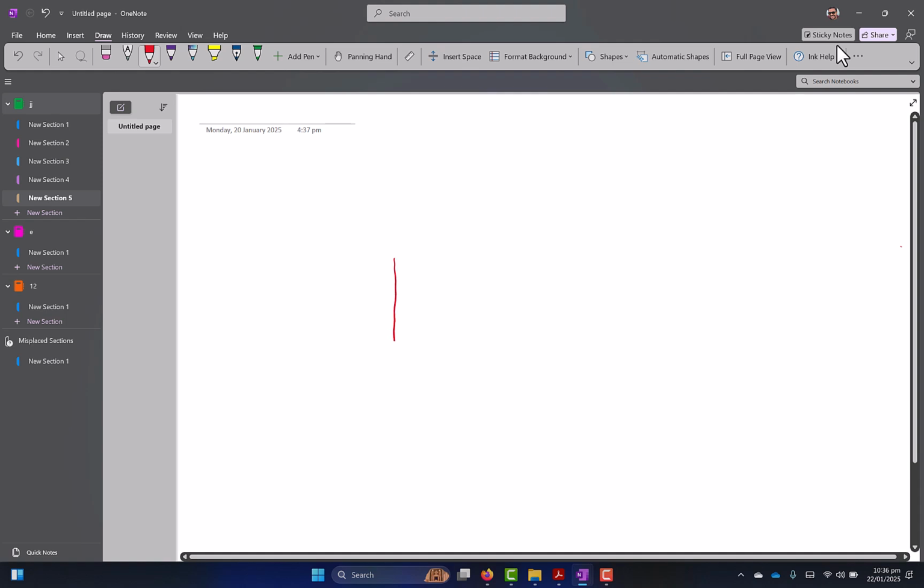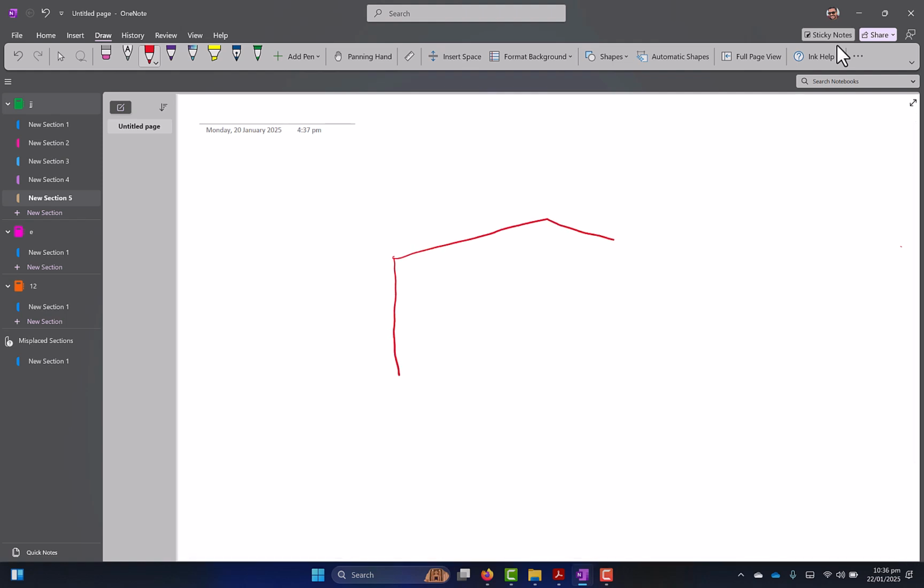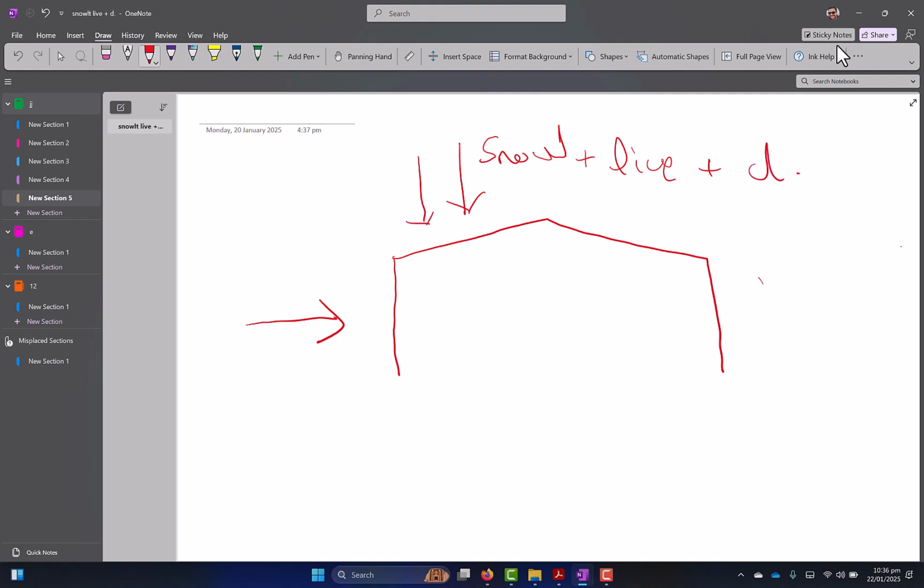Pre-engineered buildings are primarily two-dimensional structures. You have these planar frames, and the forces that are encountered are the lateral forces and the gravity forces. Gravity is snow and live and dead. So if you see, these are in two dimensions. You only see them in x and y.